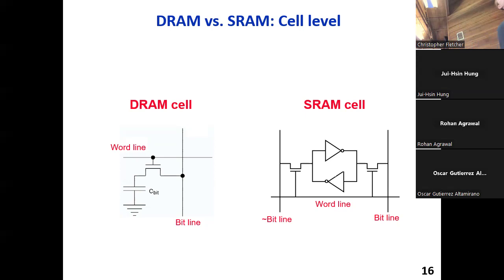So what DRAM operation do we no longer need for SRAM? Refresh, that's exactly right. We have these cross-coupled inverters, which means that if you store a 0 here, you're going to get a 1 here, which is going to propagate a 0 here, which is going to reinforce a 1 here. Much like mercury delay line memories, just a lot more modern. What this does is self-reinforce the bit that is stored there, which means that instead of thinking about an SRAM cell like a leaky bucket, you can think of it as a faucet that is perpetually dumping charge into the system to restore whatever bit value is there. So no refresh, no more refresh.